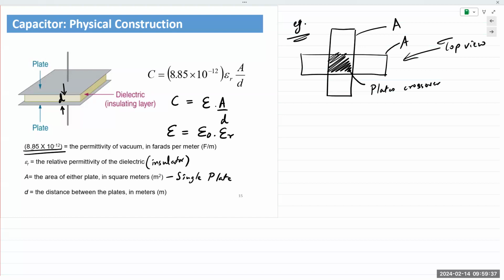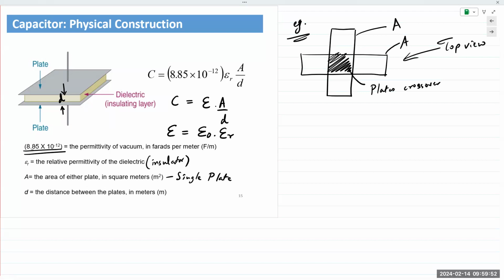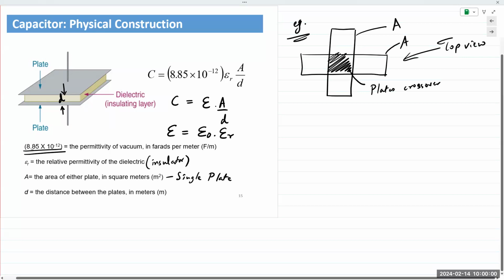And so each of those wires is separated by an insulating material. So you might have a conductor running from point A to point B, another conductor running from point C to point D, kind of like a bridge separated by an insulating material. And so the crossover section in that microchip is a capacitance. And so that causes issues with circuits. That's part of circuit design.